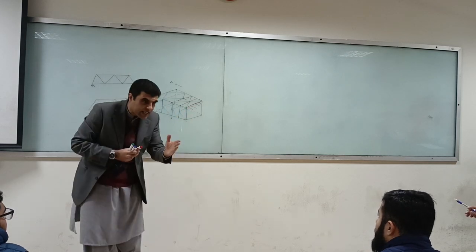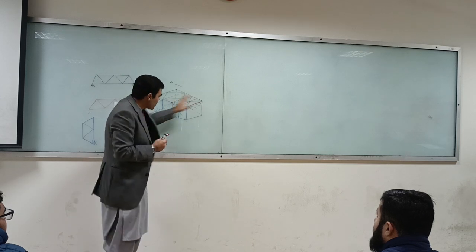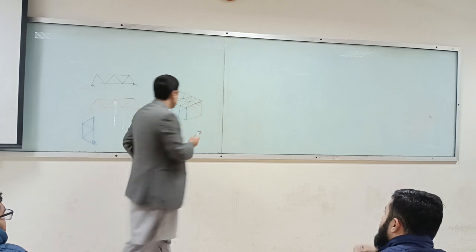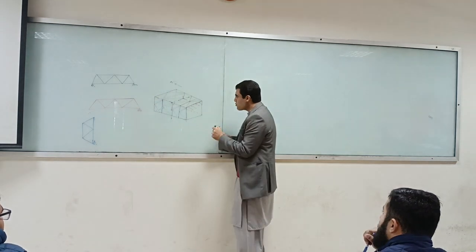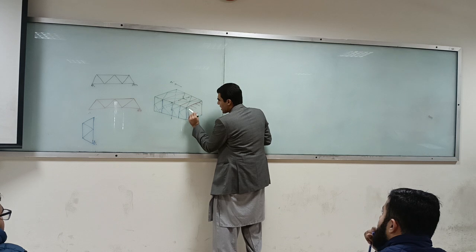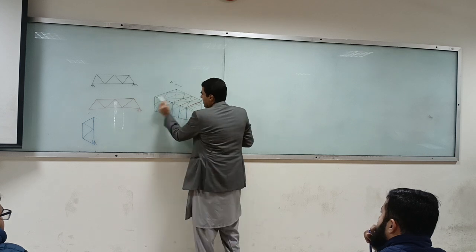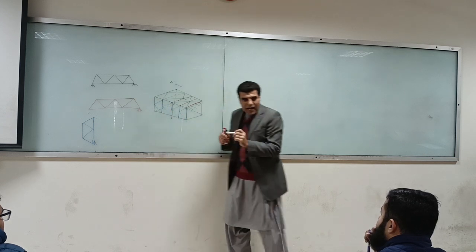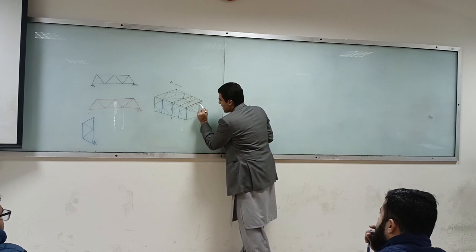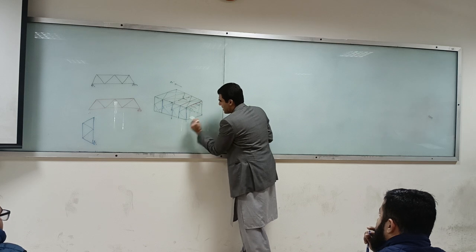So you are right that there is nothing which takes the load unless and until we provide a diagonal brace. So we have to provide some diagonal brace at the end which can go like this. Normally what happens is that people provide at the end something like this and then they brace it up.